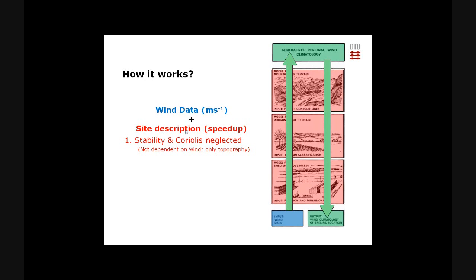The other assumption we make with the CFD calculations is that when we do these tile calculations, as Morten showed us, we are also calculating a mean large-scale roughness, this reference roughness. So we actually have a representative roughness, and we categorize our CFD speed-up calculations using this reference roughness. Thereby we can do CFD calculations independently of each other, and they can later be connected via this reference roughness.